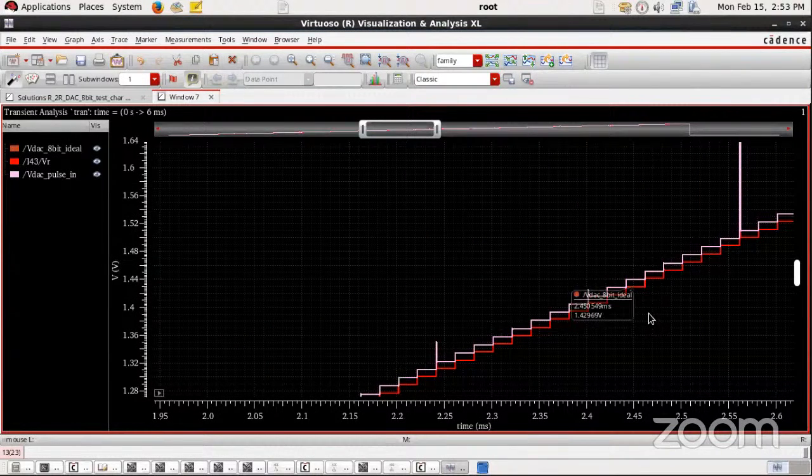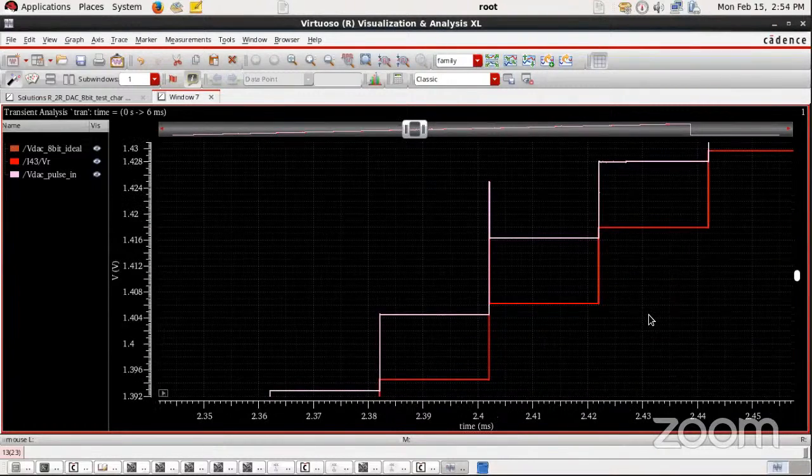So with this, you'll be able to measure DNL and INL that is associated with the mixed signal designs. When both the steps are in sync with each other, then there is no DNL or INL. If the difference between the steps is less, that is in the negative value, then you'll have a DNL.